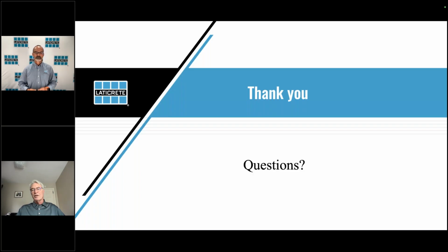Someone's asking how were the steps installed? I mean, do you have time to go through that whole installation process? We'll have videos on that, but what's nice is, let's say this is your bottom piece, and you've got your step coming across here. You pop out this tab, you've got your riser coming down, and then behind that you've got your next piece that's taller that has your tread up here, and then you're adhering your riser top to that.